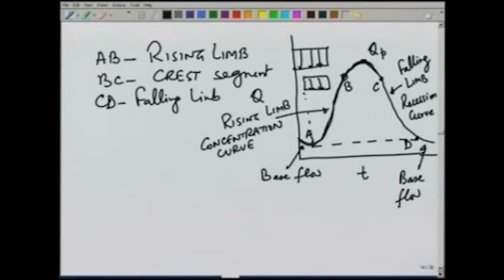From the point A, the effective rain starts, stops somewhere, and the peak will occur after the stoppage of the rain, because when the rain stops, the areas which are remote from the point A would take some time for that water to reach the point A, and therefore the runoff will continue to increase even after a stoppage of rain.